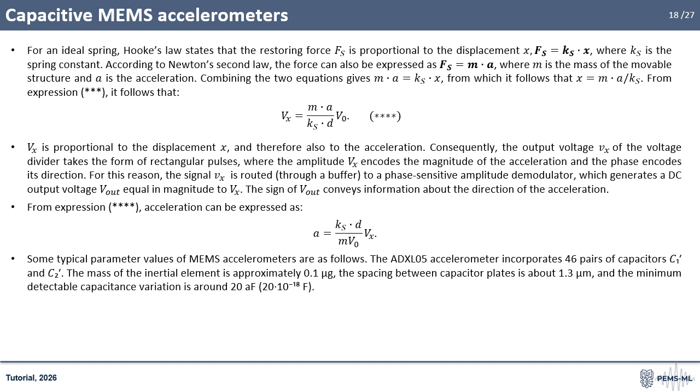A key challenge is cross-axis sensitivity. Acceleration along one axis can slightly affect the other axis's capacitors, causing undesired capacitance changes. Careful MEMS design is needed to minimize this and ensure accurate measurements.